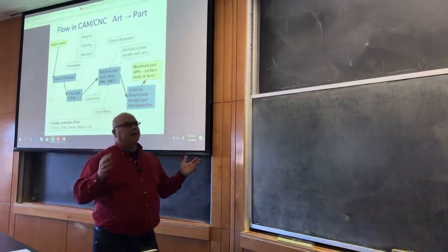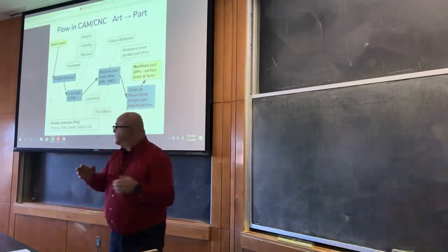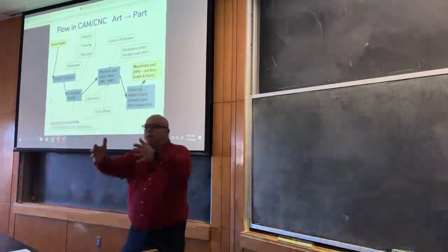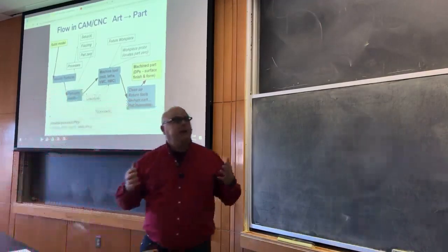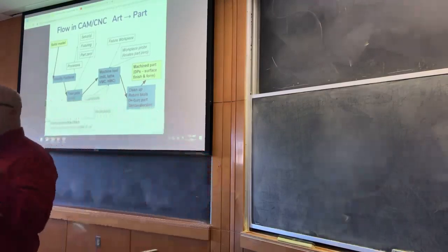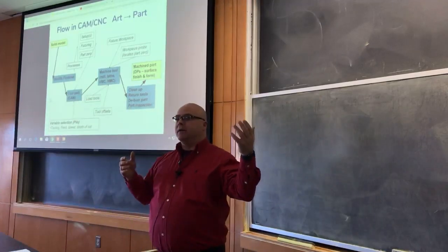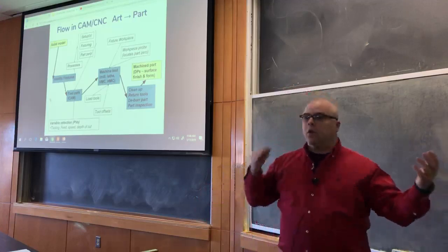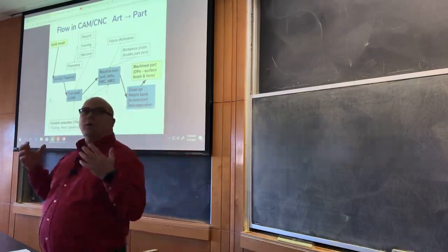This diagram presupposes that we've decided to do CNC machining, because we talk about things like tool paths. So once we've decided to do CNC machining, the first thing we do is figure out what process or processes we're going to use to make this part. Our Y block, the example part we were looking at, we could do in 2 operations in a CNC mill, or 3 operations, depending on how you wanted to do the fixturing.